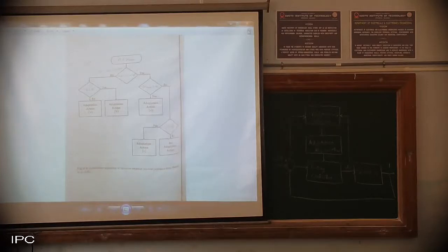Why do we need to do it at the earliest? Because the system is tuned online. When we are doing it online, the response time is very important. That is why membership function tuning using performance criteria is one of the most important things in adaptive fuzzy. Now, as I said, this is nothing but a performance based FKBC, that is fuzzy knowledge based controller. Why are we calling it performance based? Because depending upon the performance of the controller, we are going to take the corrective action.